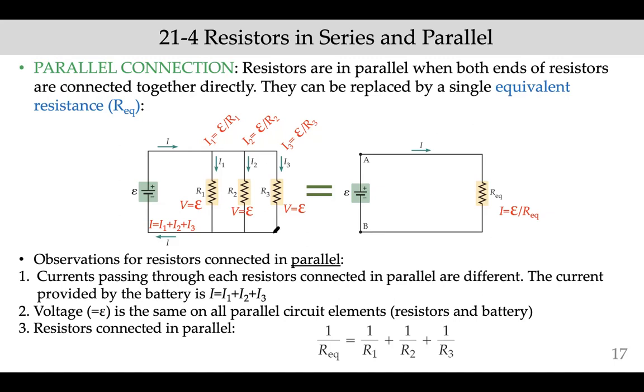resistors connected in parallel. Now again, when you're given the voltage, if you want the current that's coming out of the battery, you would use V equals IR. But since you have different R's, not just one, there's an ambiguity. What are you going to use for R? What you have to do is calculate the equivalent resistance again.